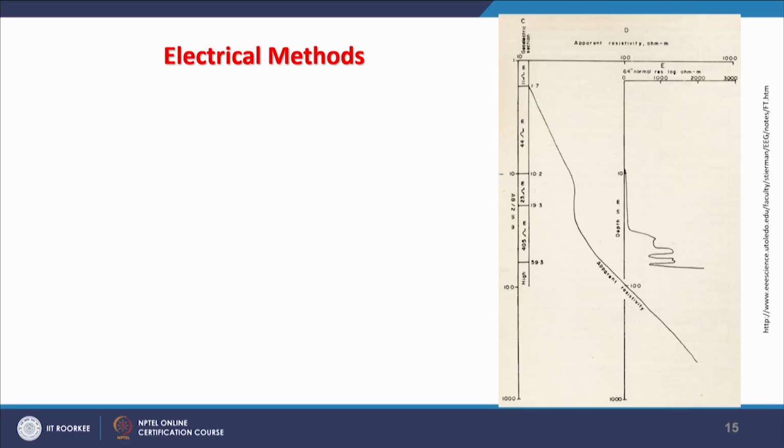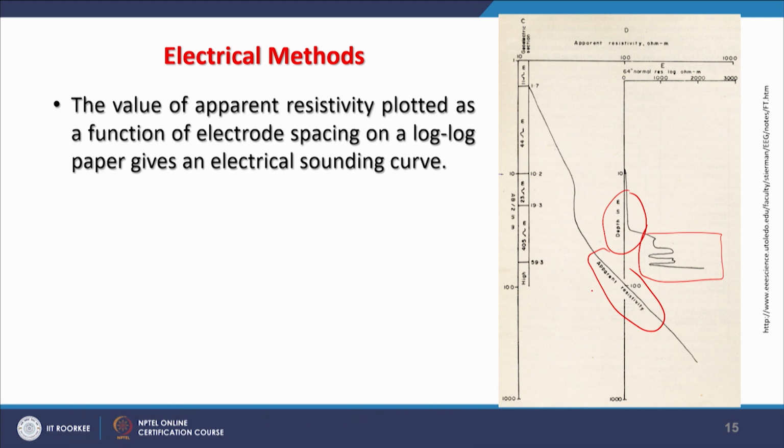Now, as we can see, this is one representative plot, which is showing the apparent resistivity in the form of a curve, and depth in meters is also shown. It is saying that different rocks will behave differently. So, here all of a sudden we are having different kinds of rocks. This curve is representing how apparent resistivity is changing with depth. With depth, that is important. So, what we are having here is that in this case resistivity with depth is increasing, but may not be in all cases. It might be just a reverse scenario also.